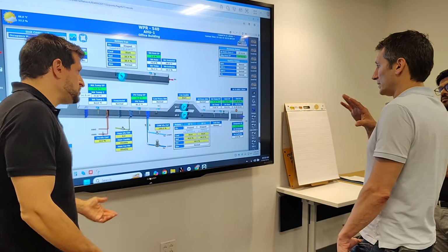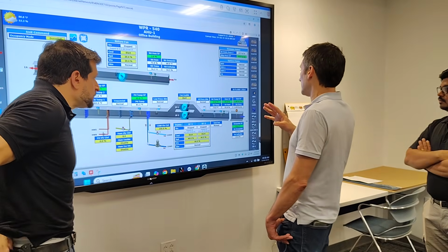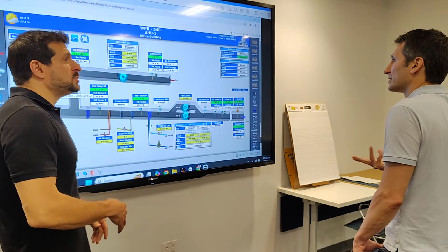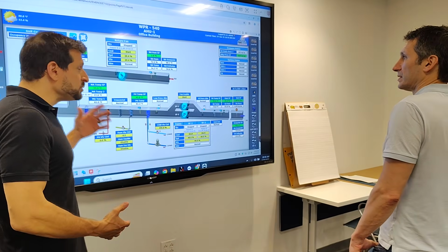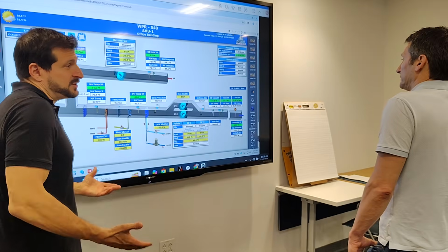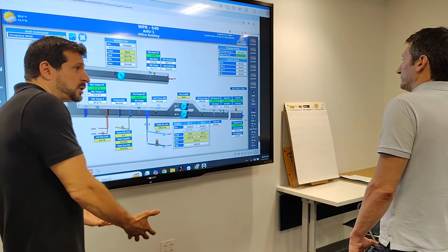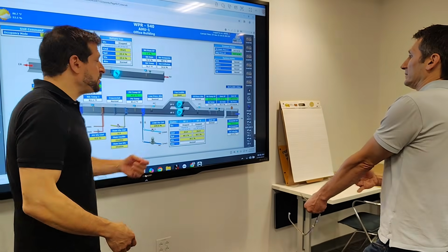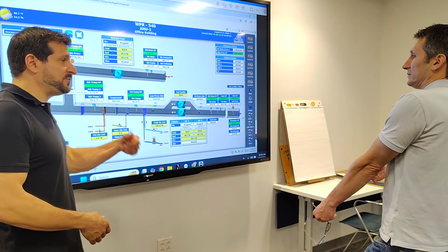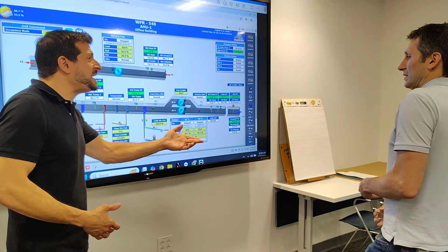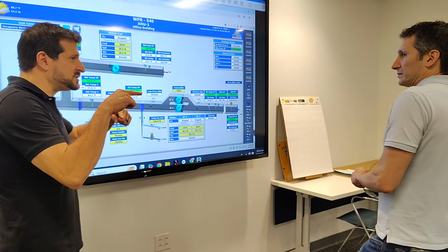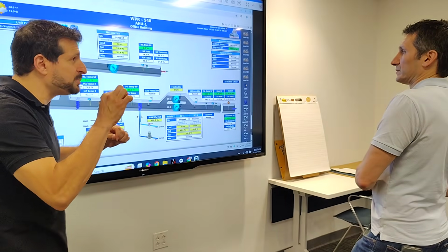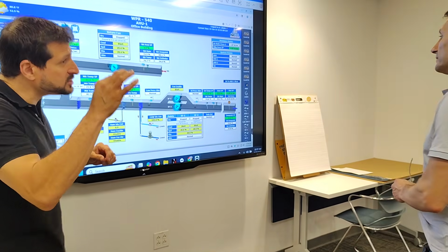Well, I get it's not tuned, but can we get it to at least work, whether it's inefficient or not? It's not about inefficient, right? The only way automation works is if you tune. You have to make it work properly. So, for instance, he writes these codes, right? Then we get on a job, and he logs into the job after he wrote the code, and he sits there for a day, 2 days, changing set points and seeing how fast it gets there and if it holds or if it overshoots, and he adjusts his proportional band, he adjusts his integral band, he adjusts his derivative band.